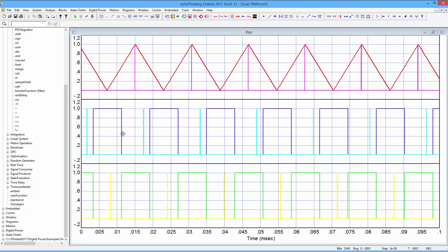In this way, we know that when we switch on, the start of conversion is separate from the switch on and the switch off. The measurement from the ADC should in theory be free of the switching noise that occurs here, regardless of the duty cycle. Even if we go up towards the period, we're going to get a maximum duty cycle, and a zero duty cycle when we go down. In that way, if there's any switching noise, we don't see it when we do the conversion of the ADC for the output voltage regulation.